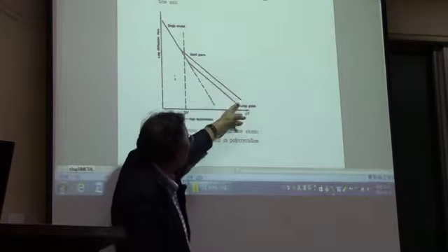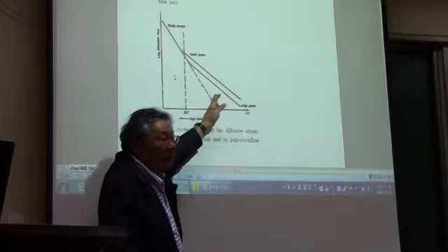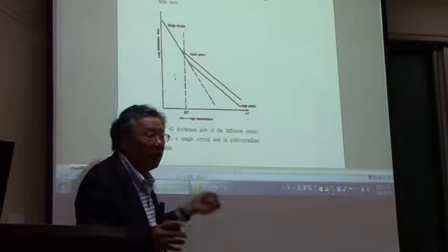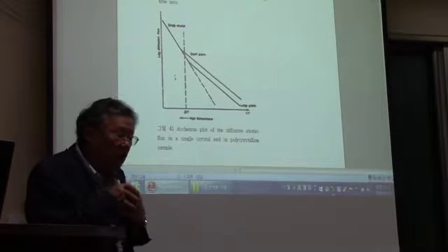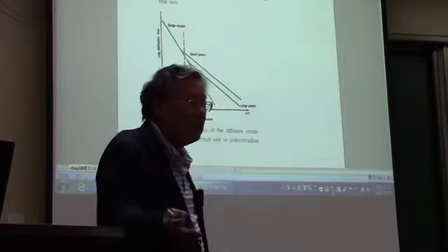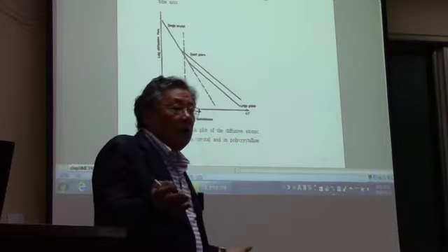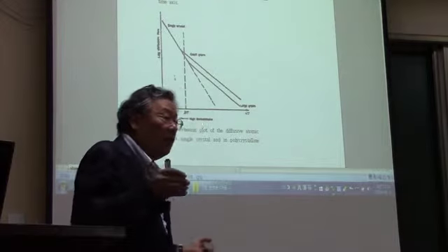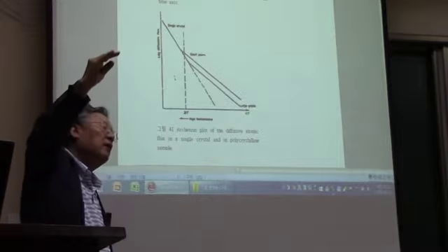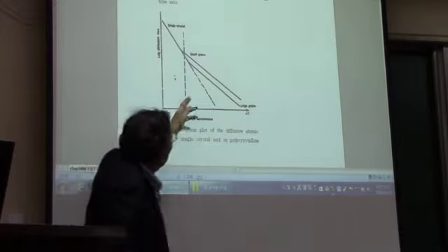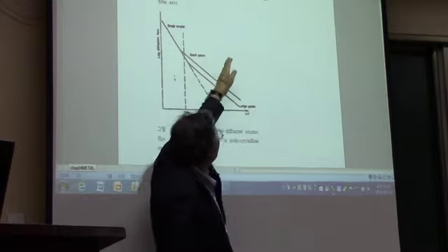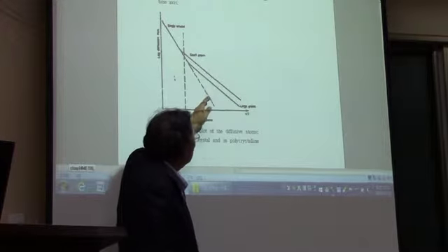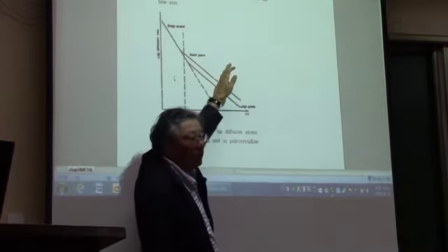the diffusion coefficient that we measure is very sensitive to the grain size. Okay, if you have a small grain size, then you're going to have a large grain boundary area, so you have a higher diffusion coefficient. So in this slope, as you decrease the size of grains, this line is going to move upwards.